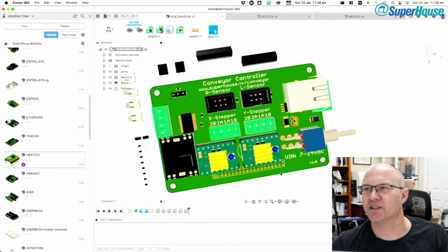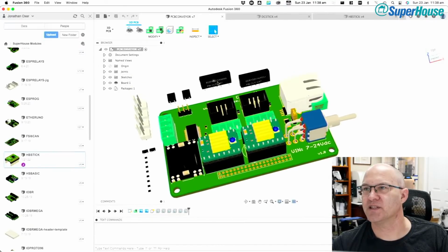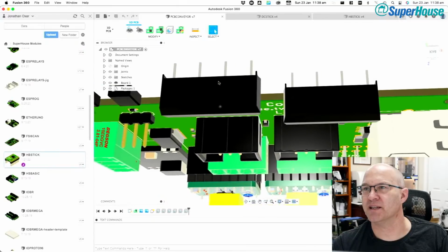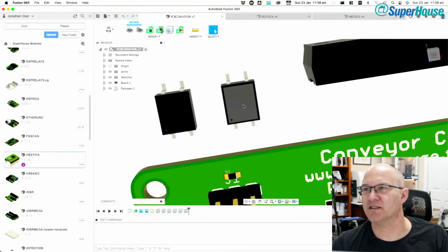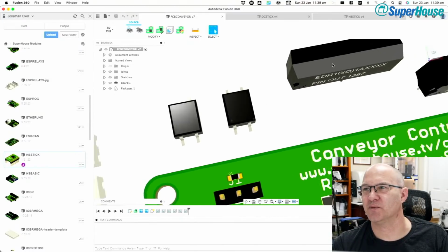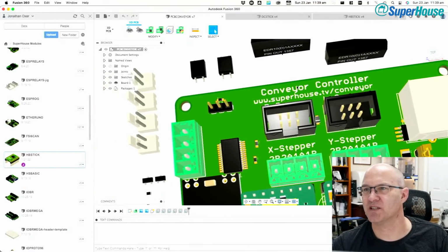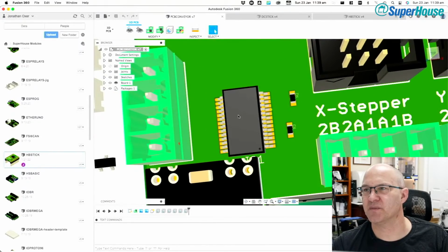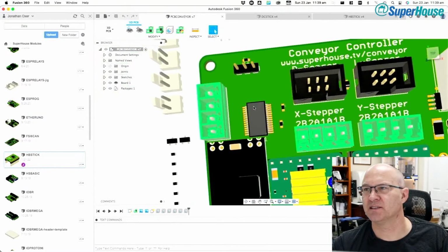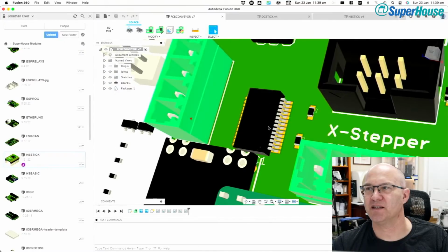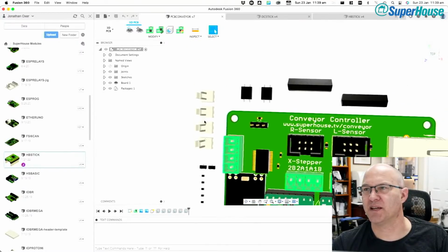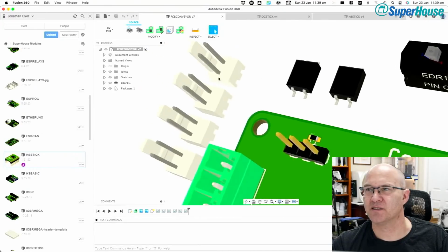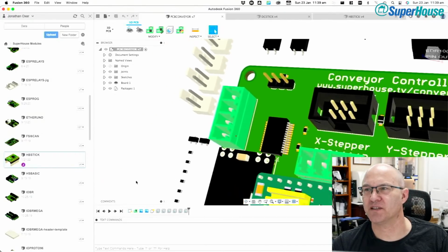So what I've got here is, these are the reed relays for the ready out connectors, and then I've got opto-isolators here for, which one is it, ready out or ready in? I can't remember. Anyway, opto-isolators and relays, those are for the connections to the adjacent machines. This is the MCP23017 I/O expander, which I may replace with a 23008 just to make it physically smaller, because I don't need all of those inputs. Just as placeholders, I've put in these connectors. So these are the connectors for the ready in and ready out on the left end of the machine.